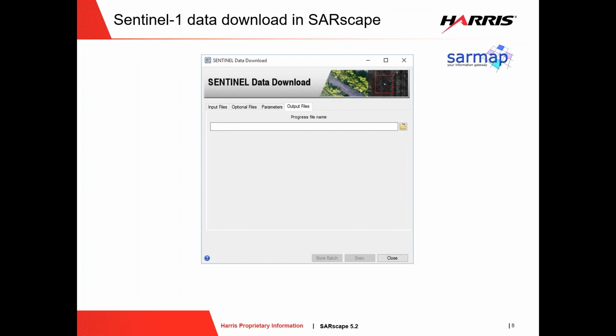Then you will provide a progress file name. This file will contain all the information about the files that have been found and downloaded. If you repeat this query some time later and provide the same progress file name, the module will identify the files that have already been downloaded, and so will work in an incremental way, updating the results of your search and downloading only the new files of interest for your project, for your application. So this allows you to continue to monitor a certain area and download only the new files acquired regularly by Sentinel on the same area.